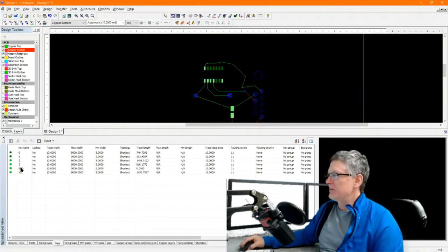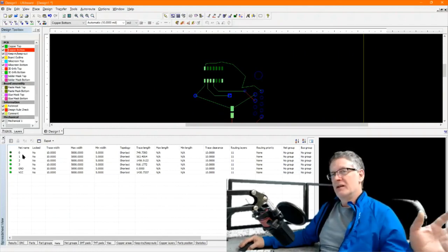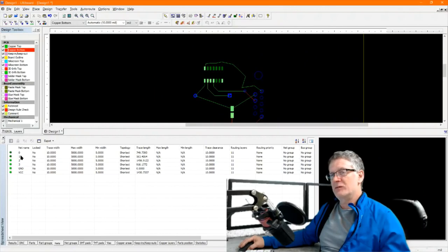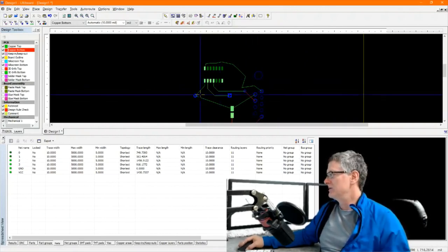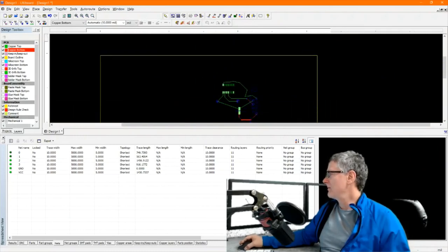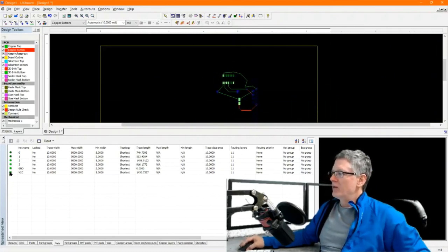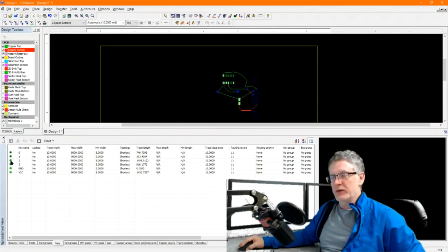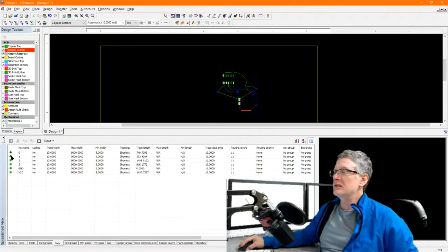And I think that I've missed one, because if I look down at the net list, there are 6 nets listed, which means there's 6 wires on the circuit board that need connecting up. When you start completing the net list and you fully route a net, it turns bright green. So these bottom 4 here, those nets are completed. You've routed them 100%. These 2 here, you're missing something with those.